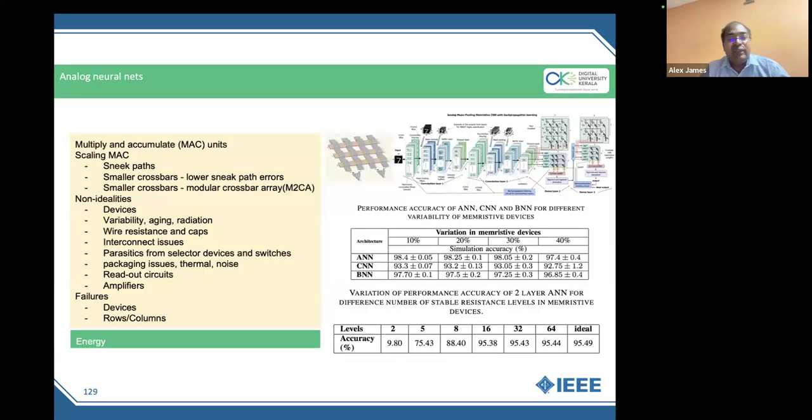And another question is, is variability bad? And the thing is, variability, you would see that when you are looking at it at system level, it's not that bad. At device level, definitely it is bad. You wouldn't see the readout. Readout doesn't make any sense. Whereas once you start putting it together as a system and start compensating it, whether at a circuit level or at an algorithmic level and things like this, you would see that it's tolerant. Many of these architectures are tolerant to all sorts of different noise.